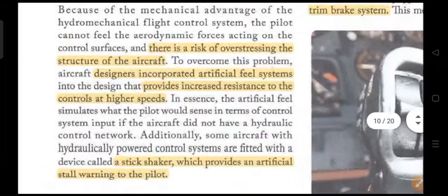Where mechanical and hydraulic systems work together, there is a risk of overstressing the structure of the aircraft in some cases where, let's say, the pilot is not understanding what amount of load he is actually applying on the aircraft's control surfaces. So designers incorporated artificial feel systems in order to make the pilot understand what amount of load he is applying, so that he does not bang too much, and does not hold a particular control column for a long time, which is going to apply a lot of stress on the structure because of the aerodynamic forces acting on it.